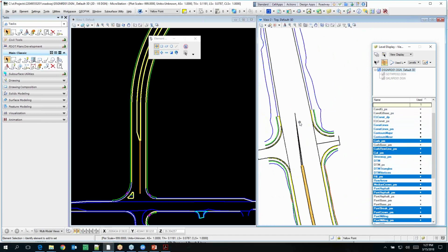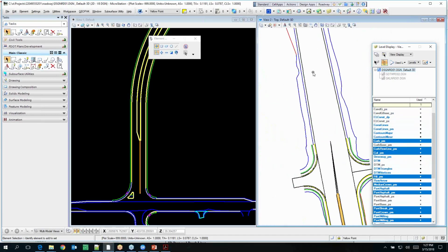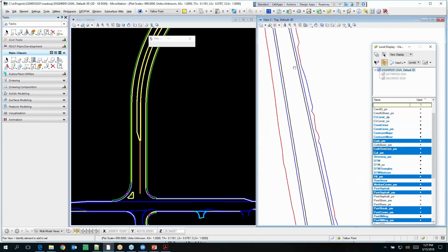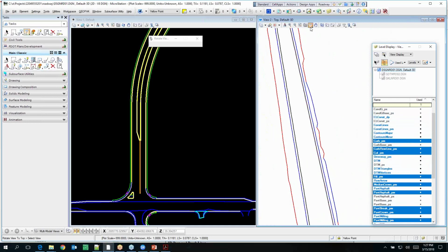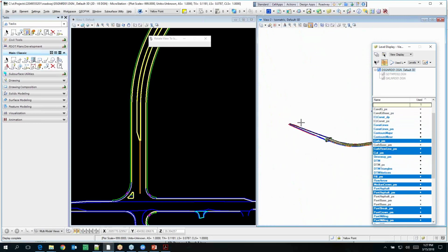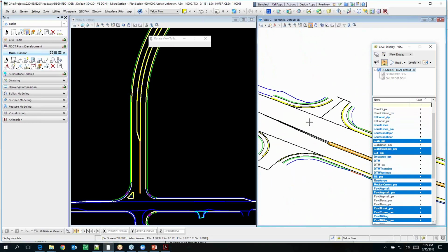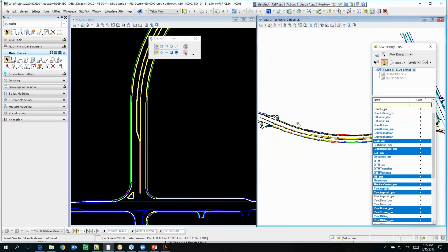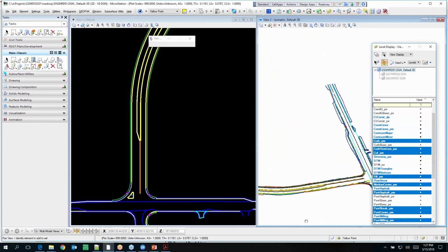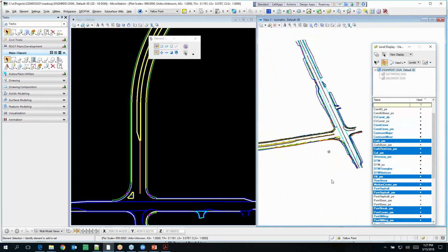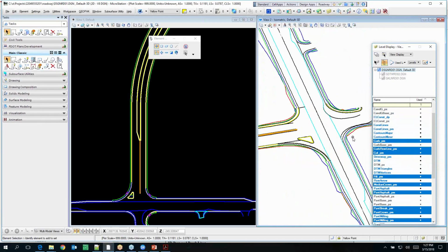And you can also rotate it after you've got it, just to look at it to see if it looks decent or not. Yeah, let's put it on isometric view and make sure that nothing looks out of place vertically. Should all be in 3D. If you've got anything at elevation 0 that's way down here and shouldn't be in that model, you need to get rid of it.